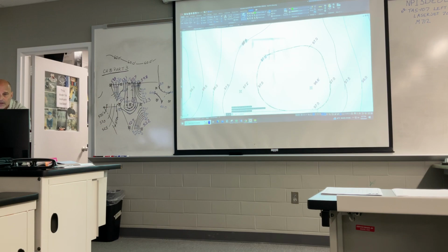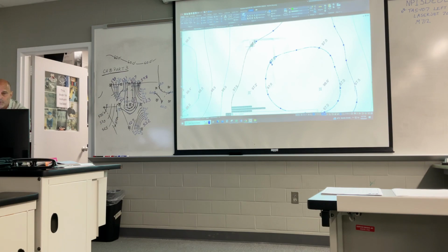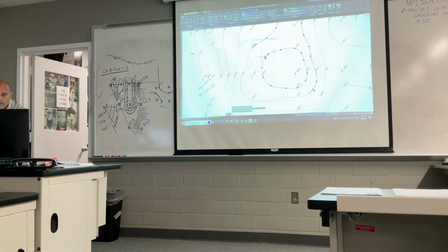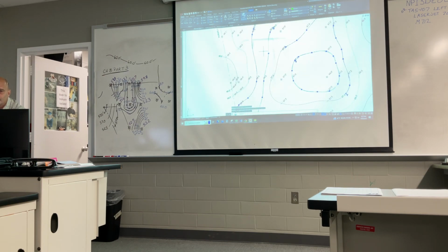You can see right here, here's a contour, there's a label right there. Here's a contour. The black number, that's a label. The red number just happened to be a tick mark that was right there by my label. You can see that on this one right here, it's a circular shape. So this one hit in multiple boxes around here and curled back to itself. You will see there's a lot of different variations in your lines here. I've got 3 or 4 different options shown on this one. So it isn't just this is how it is. There are different variations that it could be.